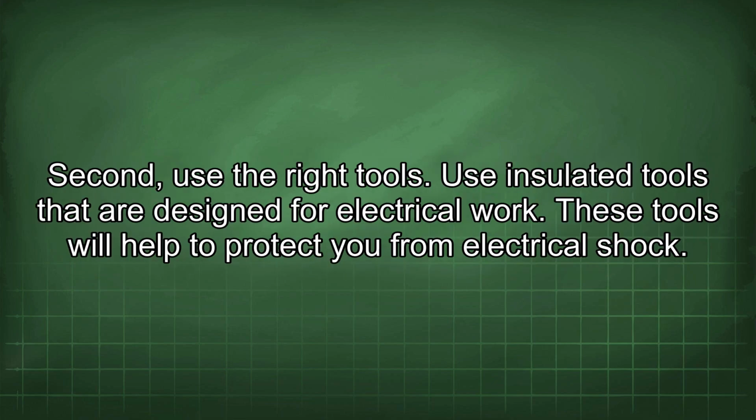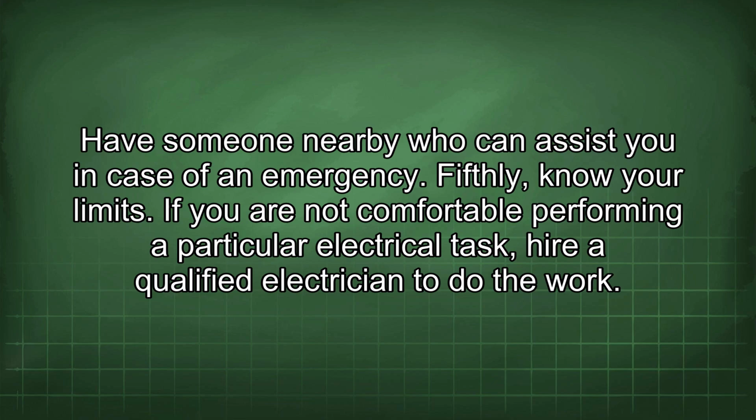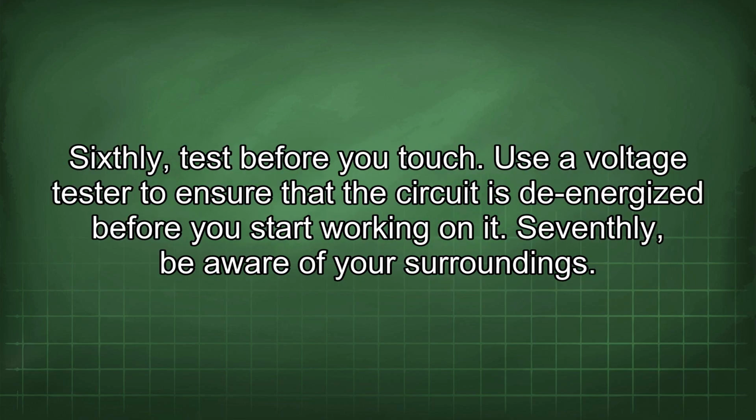Second, use the right tools. Use insulated tools that are designed for electrical work. These tools will help to protect you from electrical shock. Thirdly, wear appropriate personal protective equipment, or PPE. Wear safety glasses, rubber gloves, and other PPE as needed to protect yourself from electrical hazards. Fourthly, never work alone. Have someone nearby who can assist you in case of an emergency. Fifthly, know your limits. If you are not comfortable performing a particular electrical task, hire a qualified electrician to do the work. Sixthly, test before you touch.